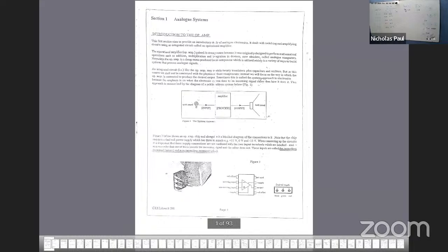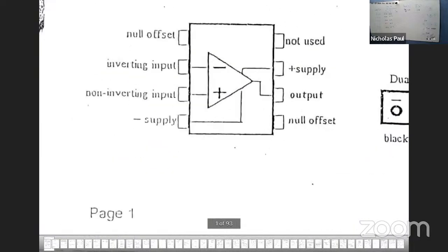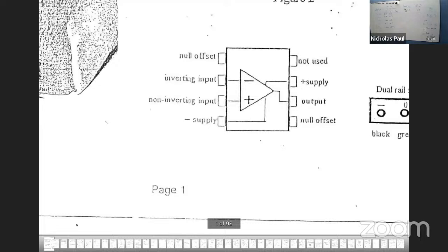Right, but with those diagrams here, we're not too concerned with that. We are concerned with this little triangle here. This little triangle here is the circuit diagram that we're going to use to represent the op-amp. It has a few components that are important. Number one, you have a triangle and you have a negative supply and a positive supply.